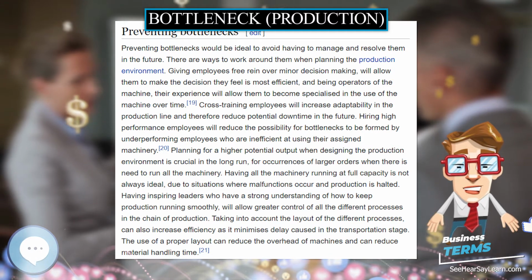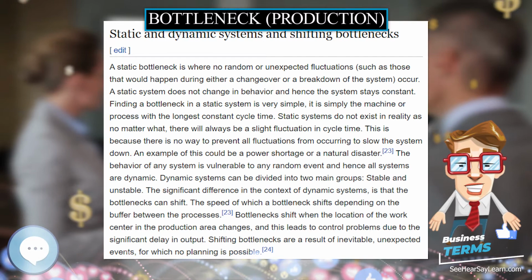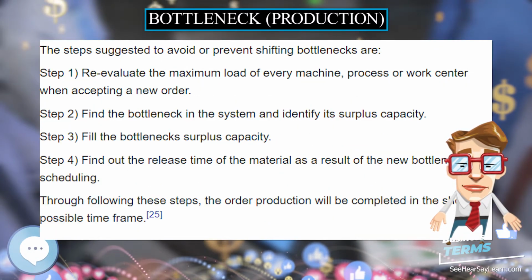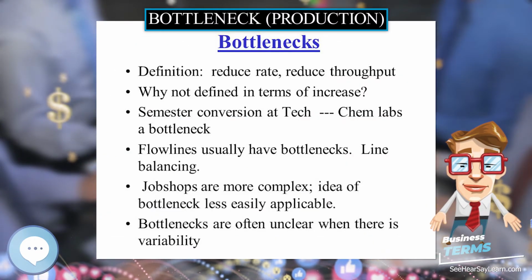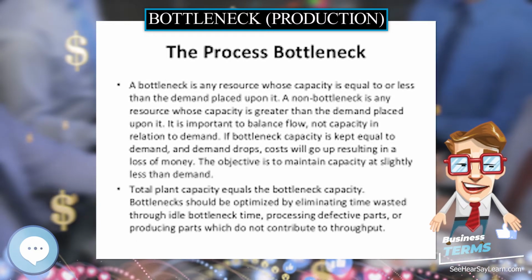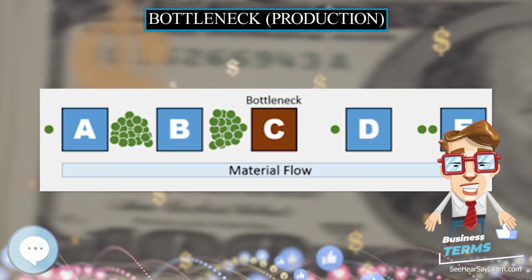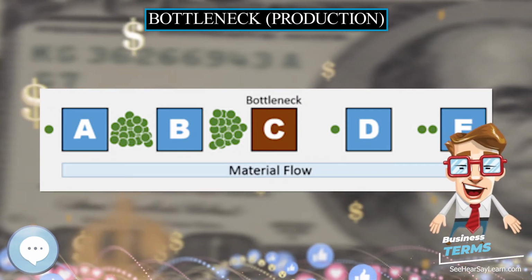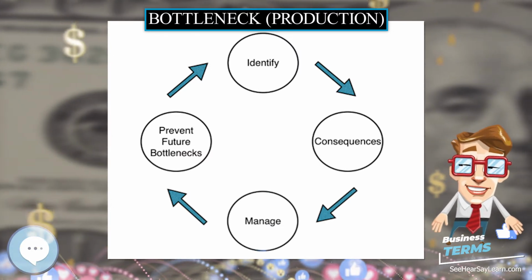Minimizing downtime, setup and changeover time. To compensate for being the weakest link in the chain of processes, the bottleneck machine will have to run for longer periods of time. Changeover and setup time should be minimized to allow the machines to run for slightly longer, reducing the impact of the bottleneck. Minimizing downtime by having the bottlenecked machines run from earlier until later is a common strategy for working around the problem. However, this does increase the likelihood for the machine to be overloaded and need regular maintenance.